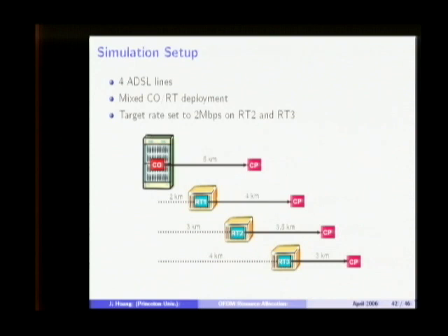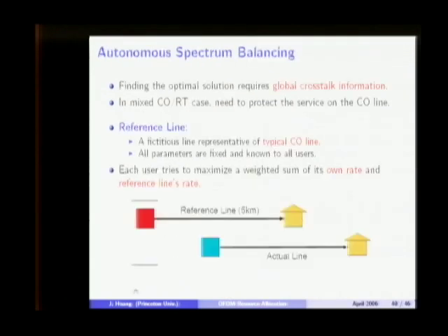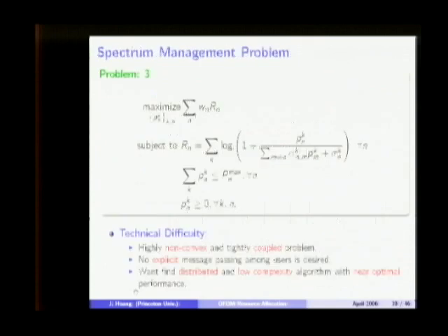Until finally, assuming the step size on the adjustment of W is small enough, they will eventually achieve their target rate. So it seems like you're using the W as kind of a Lagrange multiplier on a rate constraint. That's right. So there are 2 formulations of this problem in this community. One way is formulated into a weighted rate sum, where the W is fixed.